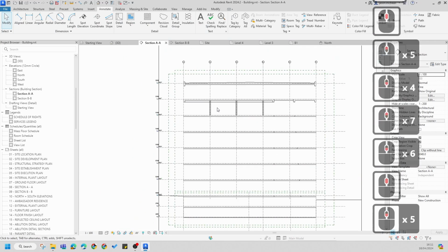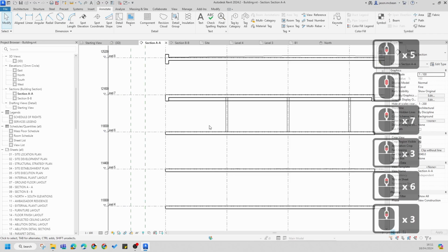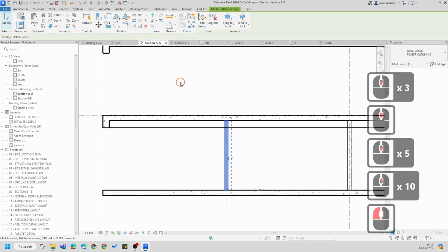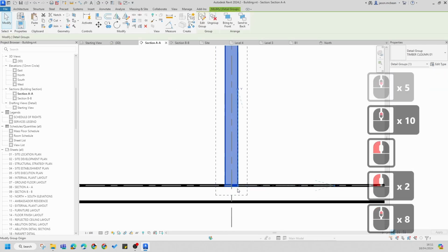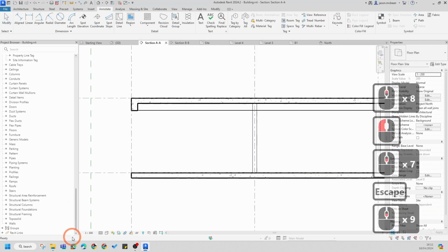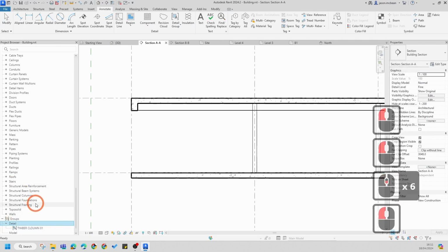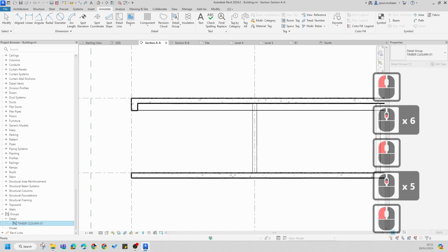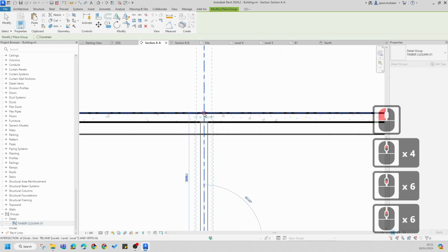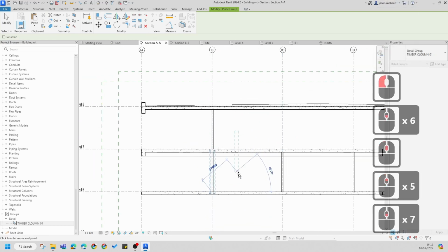But here you see I'm using basic drafting line work to get an idea of how this should work. Now this is a masking region, so if I create the same one, so if I move this to this point over here, and I go to groups and I want to use it again, groups, timber column. Okay, so if I want to use this again, I can now use it on this floor, and you'll see it gives me that point on which to snap to every time.